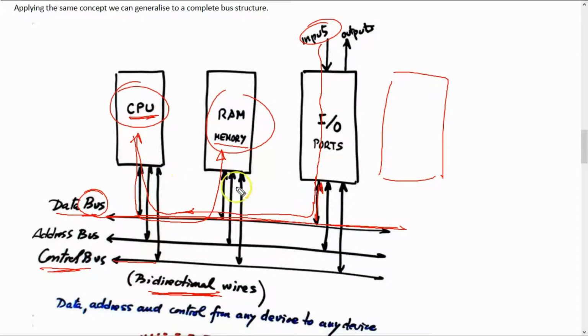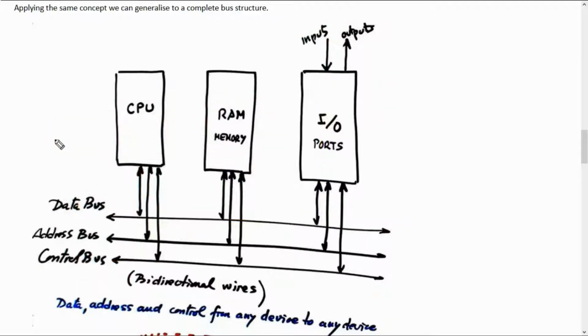Something like this is very possible if you think that internally in this structure of a microcontroller you have this idea of a bus. A bus for the data, normally in this kind of microprocessors that we are using here, an 8-bit data bus, and then you have an address bus, to pinpoint every single memory position in the RAM, and then the control bus.